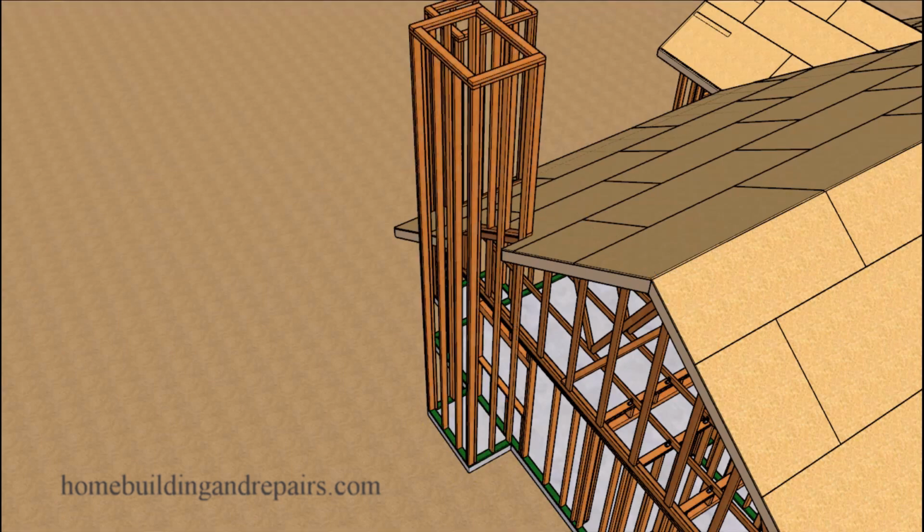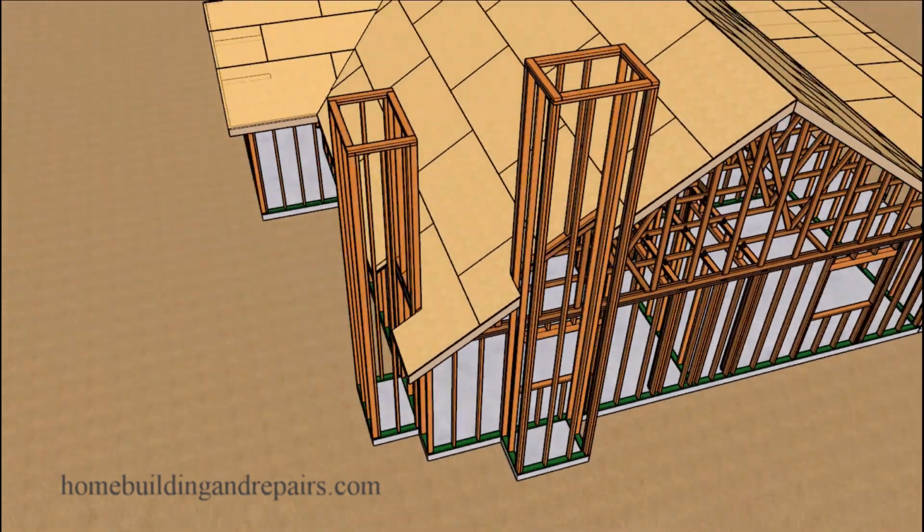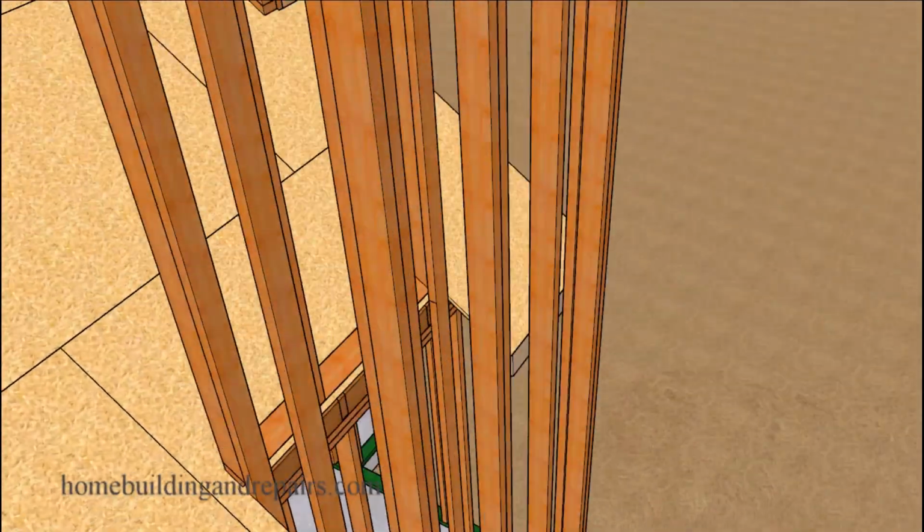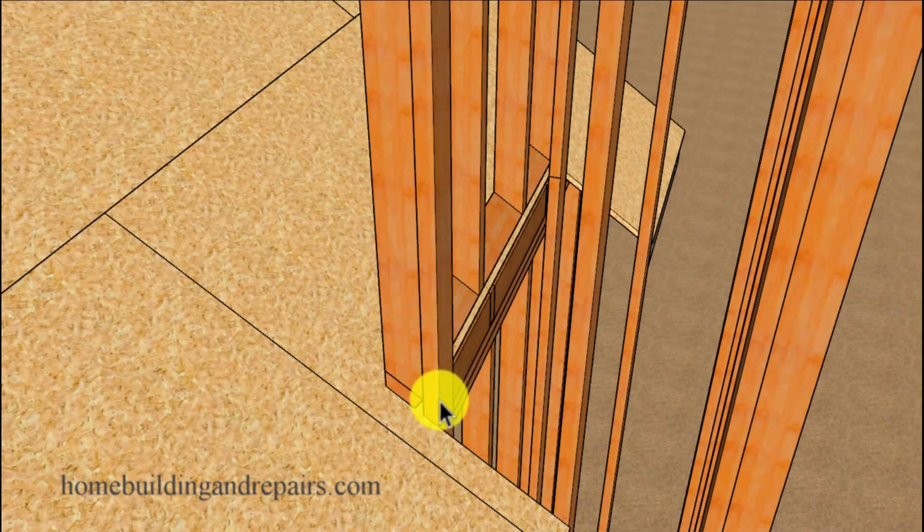And let's go ahead and wrap this video up by taking a look at the completed wall framing for our chimneys. And as you notice, this one here is a little taller than this one here. The farther you go up the roof, the taller the chimney is going to be. So keep this in mind if you're not interested in building a huge chimney when designing your project. Try to put them at the bottom of the roof. And this is probably the most common location you're going to find for a chimney, especially for home builders who know what they're doing.